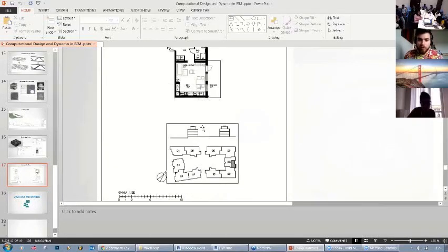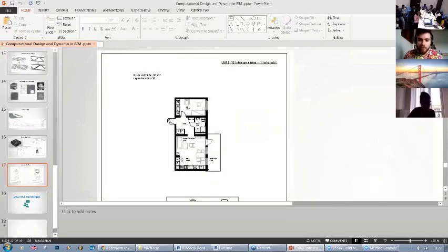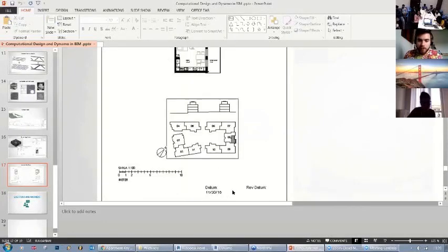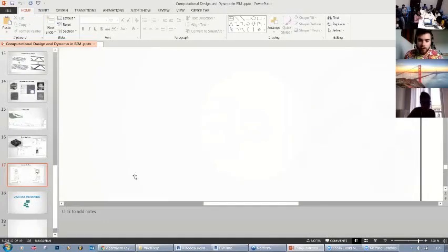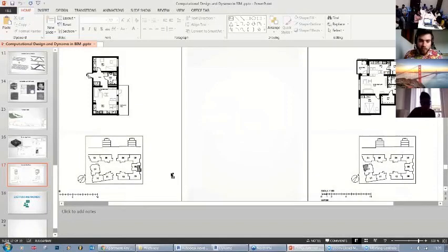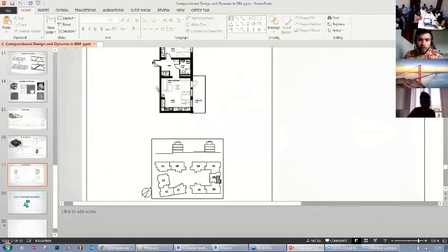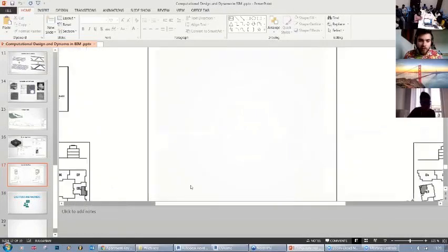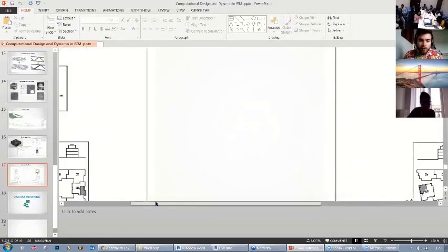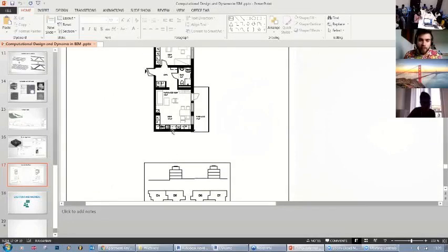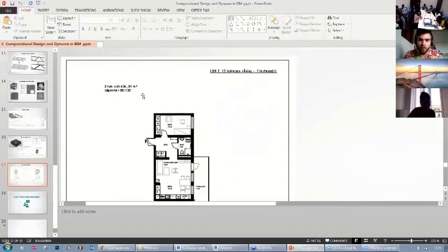So the script made that legend, which shows where we can find that apartment on the plan of the building, which is here. It also placed that arrow to show where the entrance of the apartment is. It also placed these texts that are actually the name of the apartment, because the name of the apartment was the name of the group in Revit.